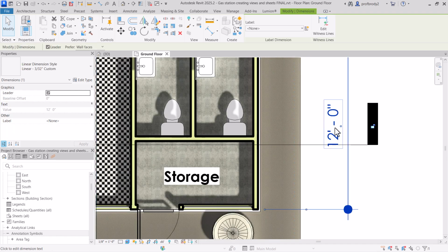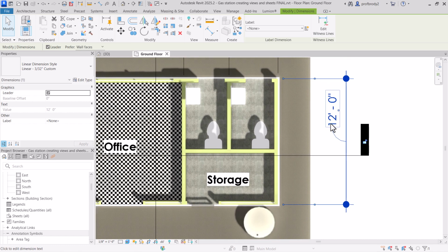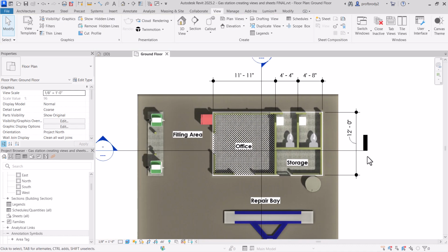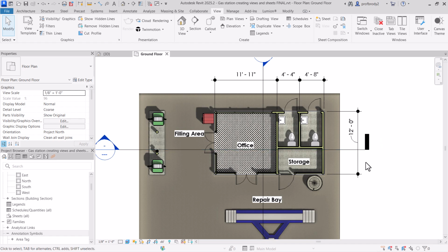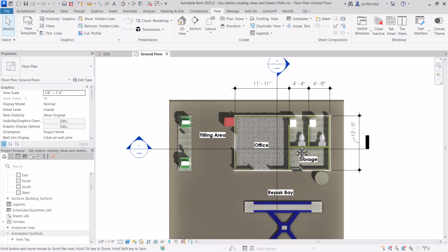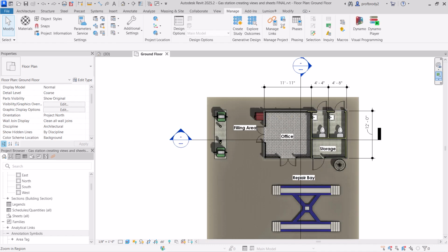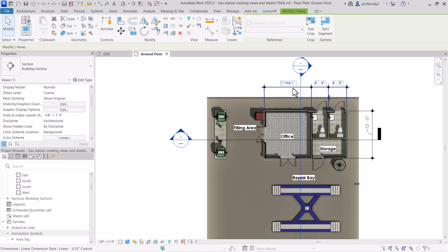Oh, finally, when you want to clean up these drawings, you can move the text. I'm just selecting it and clicking the dot on it, which is the grip. And that allows you to move it out of the way. It just makes it a little clearer when you're looking at the plan. So one last thing about sections before we actually go and look at them is that, as far as I know, there's no way to actually change the line weight of the lines going across here.